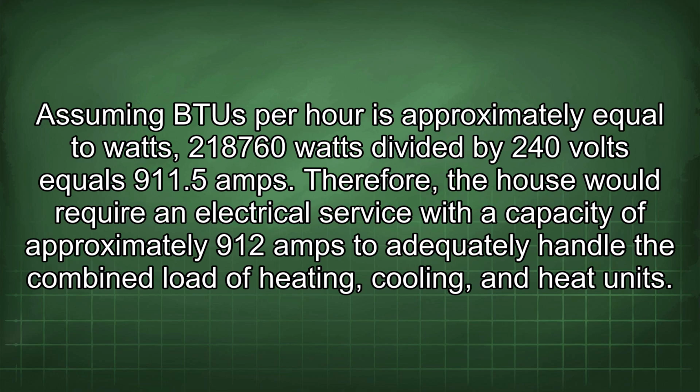Assuming BTU per hour is approximately equal to watts, 218,760 watts divided by 240 volts equals 911.5 amps. Therefore, the house would require an electrical service with a capacity of approximately 912 amps to adequately handle the combined load of heating, cooling, and heat units.